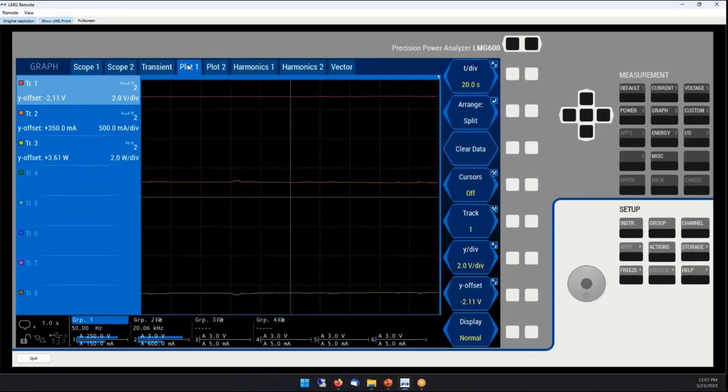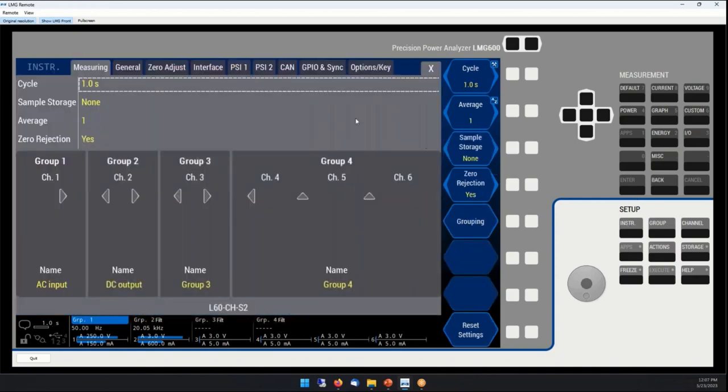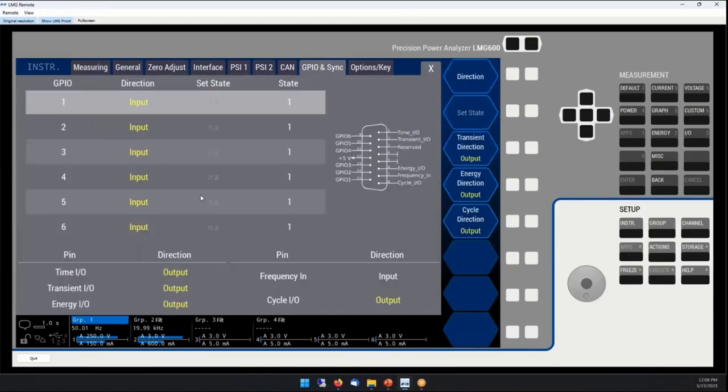And there's also, for more advanced use, something I may be able to show here on the instrument. Imagine that you build a test circuit for a charging cycle. You build a couple of relays which change your battery from charge to a discharge or to a standby mode, and you can even control these relays using inputs from the power analyzer.